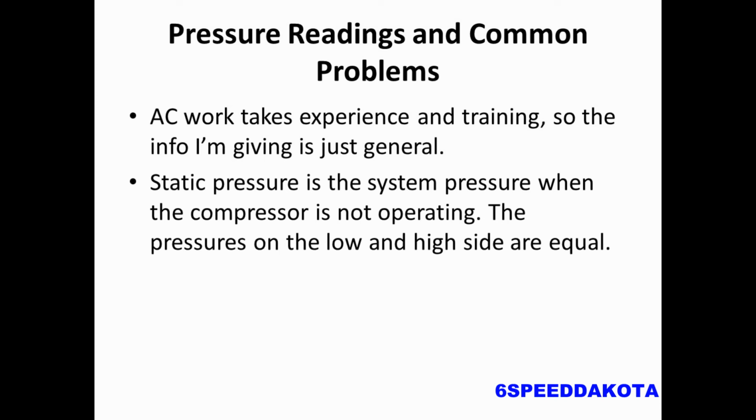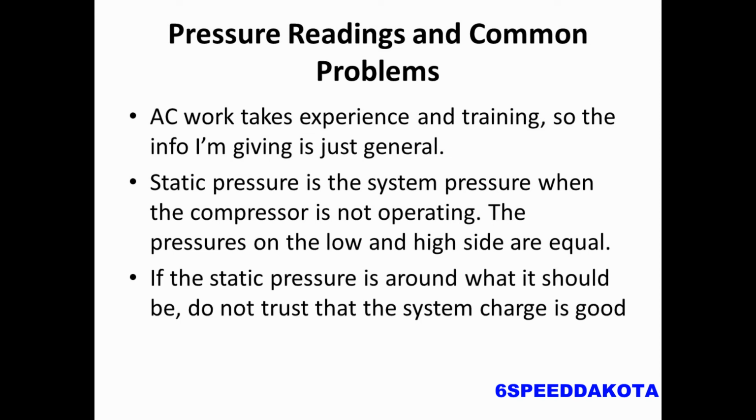So static pressure is the system pressure when the compressor is not operating. When you connect your manifold gauge set, your low and your high side should be equal. If they're not, you could have a blockage somewhere in the system, or your manifold gauge set might not be functioning correctly. If the static pressure is around what it should be for the ambient temperature, we cannot trust that alone to say that the system charge is good.